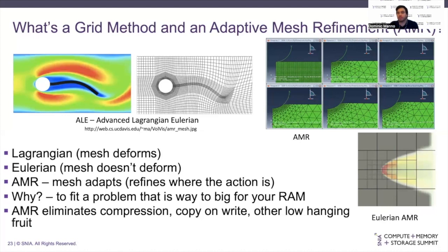So time steps are implicit in the storage system. What that means is that each time step or some number of time steps are written to storage as complete independent data sets. So because these simulations are often large, the space is decomposed somehow across these polyhedral cells, and groups of these 2-dimensional or 3-dimensional cells of the grid are decomposed onto different processes, different cores, different machines to enable parallel computation. So somewhere on the order of 10 to 100 state array variables exist in every single polyhedral.